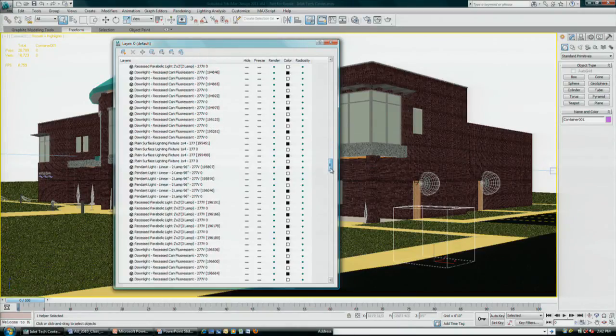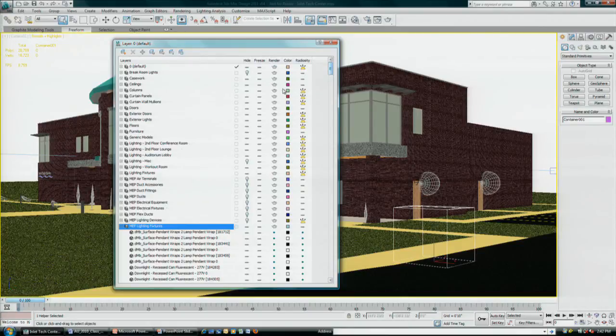And I actually did do those timings to time this. The whole model took me 9 hours to render. Just offloading the lighting that I wasn't using and backing down to a draft mode render of this thing was 9 minutes. So one tenth the time just by offloading the unused lighting fixtures.